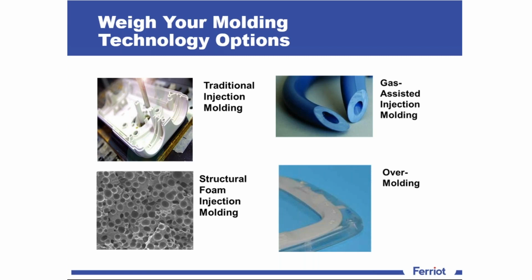The gas assisted injection molding process involves injecting an inert gas into an injection molded part during the packing stage. The process employs compressed gas as the packing medium, providing dimensional stability for thick molds and reducing warp and sink marks. This technique uses less injection pressure and can reduce clamp tonnage requirements, saving on the amount of energy and cost required to produce them.